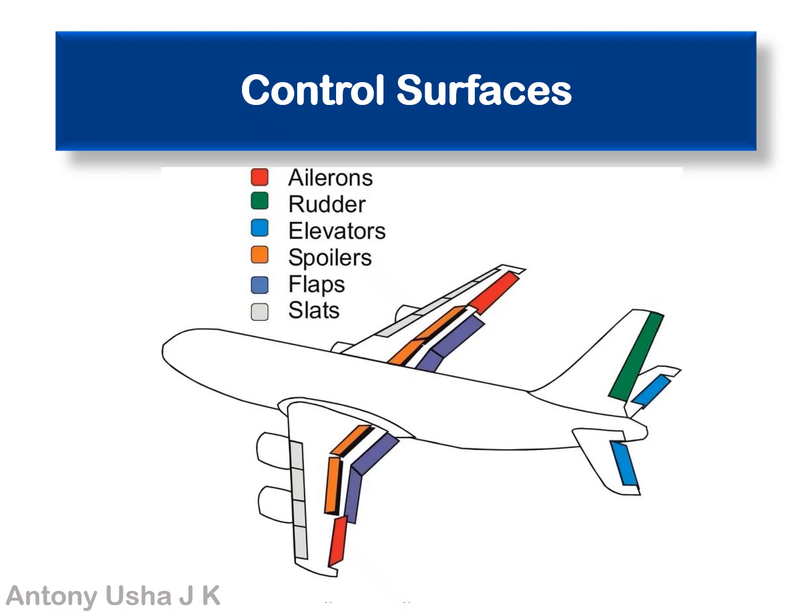Together these three primary control surfaces, aileron, rudder and elevator, work to stabilize and maneuver the aircraft across all three axes of flight. Spoilers, flaps and slats are the secondary control surfaces, which are used to reduce the drag and also to increase the lift.